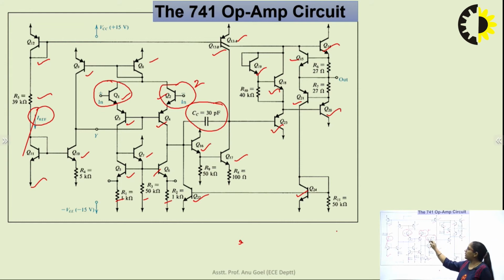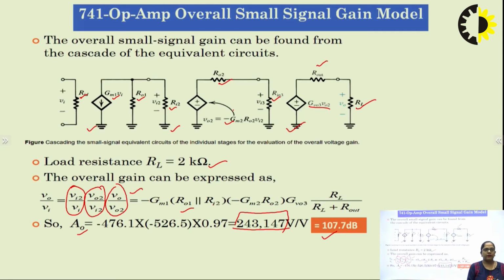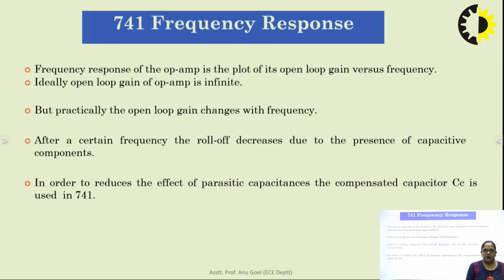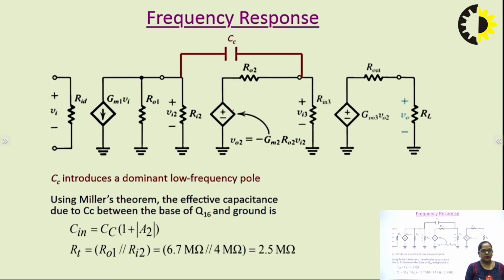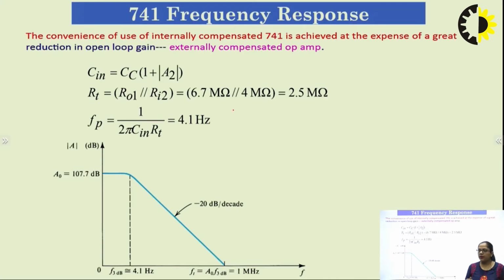So, there is a provision of internal frequency compensation in the second stage with the help of this coupling capacitor. Here this coupling capacitor is connected in the negative feedback path in the second stage, and the technique that we are using for providing the internal frequency compensation is Miller compensation technique. So, let us first observe the overall frequency response of op-amp IC741, then we will see how much compensation we can provide with the help of this coupling capacitor with the help of Miller compensation technique.